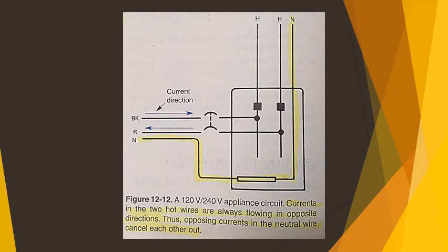33,321 VA. The service for this home will be supplied by a 240 volt single phase 3-wire system. So you have to divide the total service load by the voltage to calculate the amperage required by this home. In this case, 33,321 VA divided by 240 volts equals 138 amps. So based on the optional method, a 150 amp service is all that is necessary for this residence. Again, review the previous factors that may justify upgrading the service to a higher amperage before settling on the calculated service.